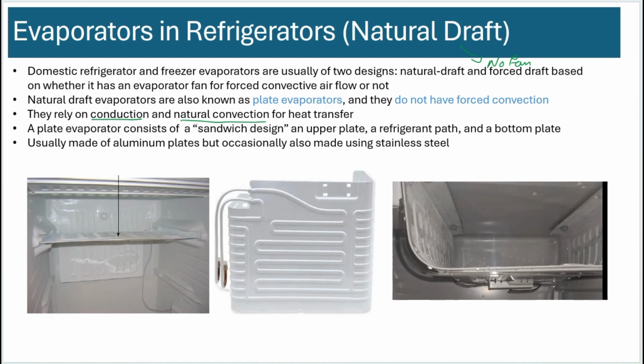So what are these evaporators made of? They're typically made of aluminum plates, and they're also made of stainless steel sometimes. You basically make these things using a sandwich type design. You have two plates, an upper plate and a bottom plate, and there is some indentation on these plates for refrigerants to go, right?